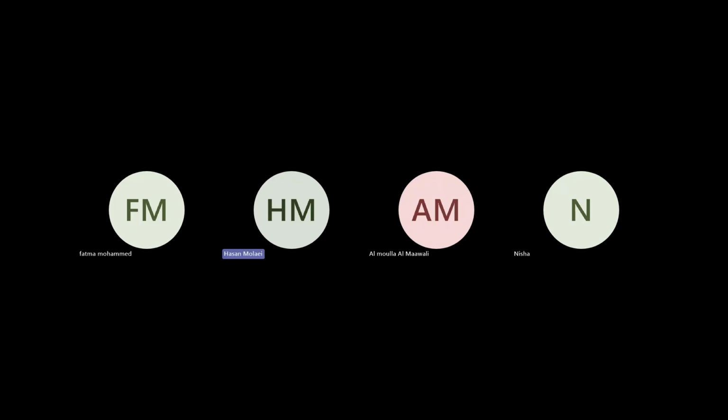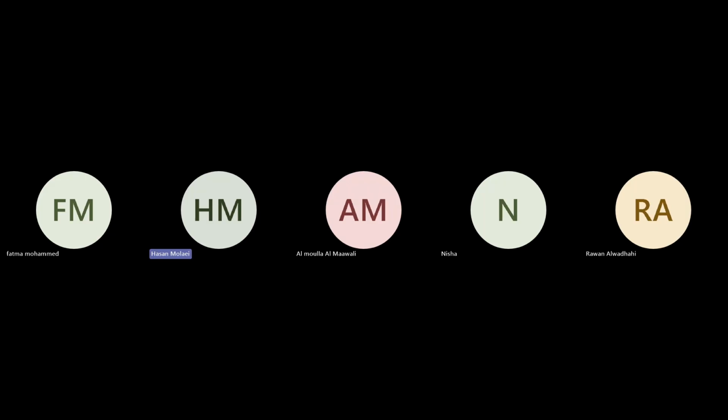If we apply a unit impulse, the output we call the impulse response. If we have the impulse response, we can find the output to any input. How? Convolution. It is the integral from minus infinity to infinity of x(tau) h(t minus tau) d tau.